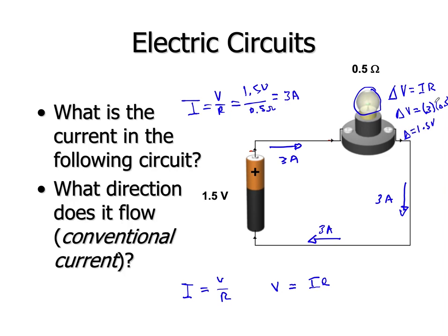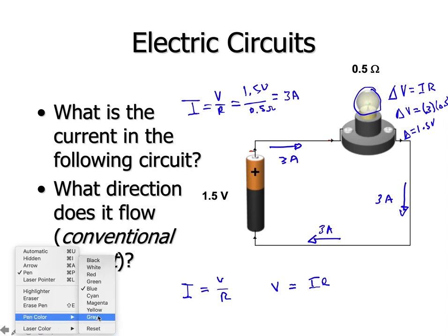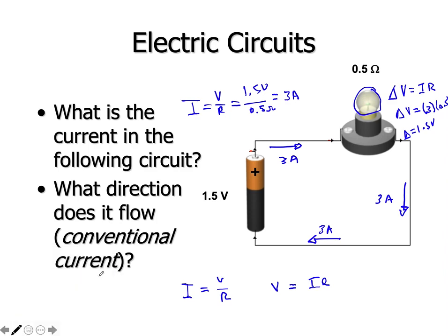So what's happening here? And this is where I'm going to leave you for tonight, and you should be in good shape: what's happening in the circuit? Well, let's say I define the electrical potential at this point in the circuit to be 0 volts. What happens after it goes to the battery? It gains 1.5 volts of potential. And that stays the same even right before the light bulb.